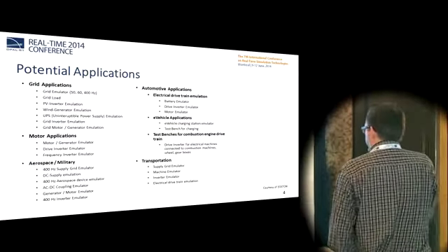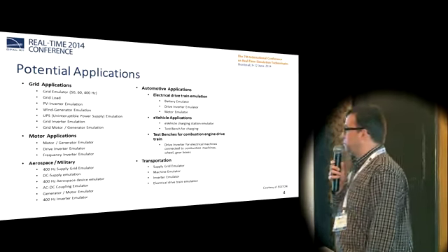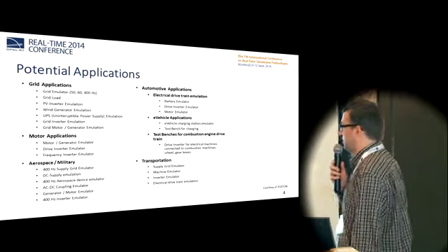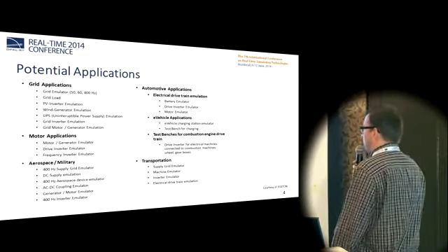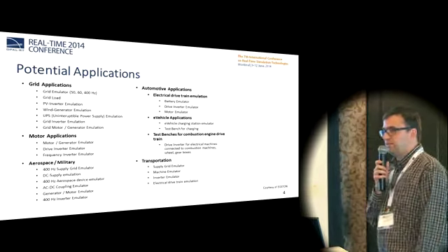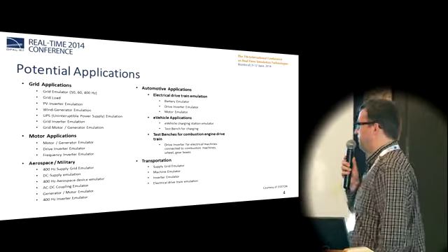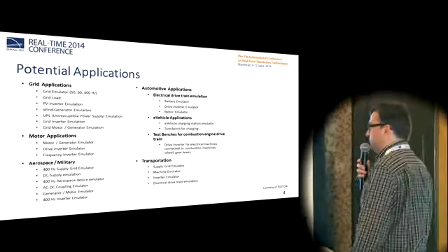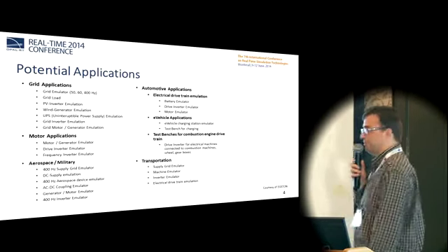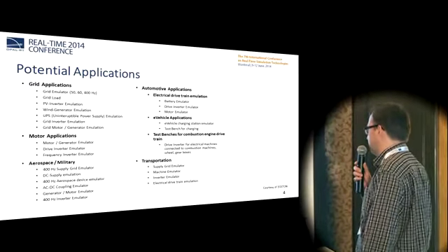A little bit about the performance, because it's also often asked. Our products, when equipped with the right software, because in principle they're completely open, you can achieve current and voltage step response times in the range 250 to 400 microseconds. That is from the start of the set point to the 90% level. If you use 10 to 90%, which is also a common indicator, then you can easily subtract 50 microseconds from those figures. But it's not that relevant.